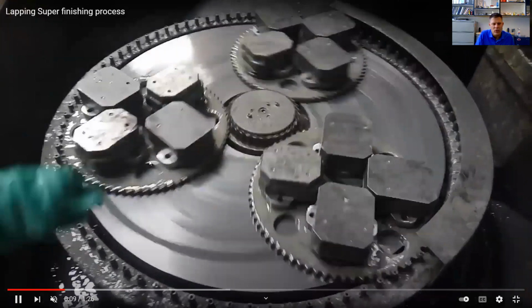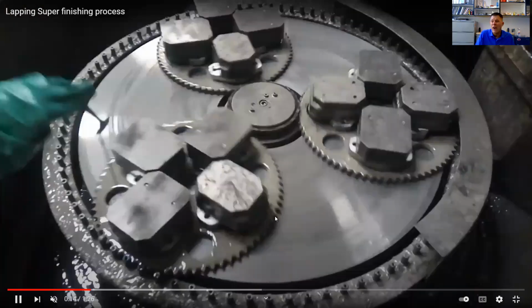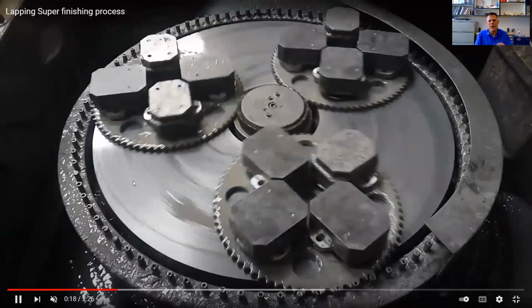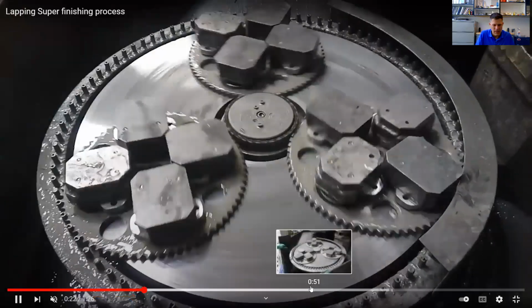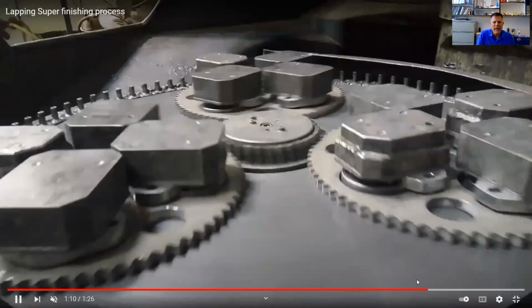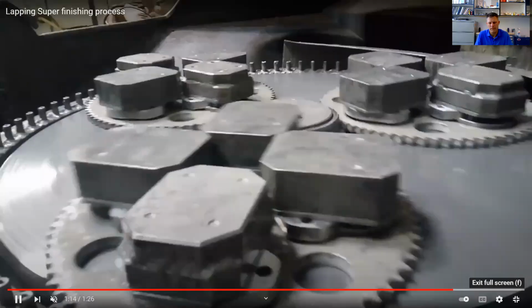The parts are underneath it. These are just weights on top of the part. The parts are actually underneath that. And all they're doing is removing a small amount, finishing the surface of that part to a real smooth surface finish. It does this for like a minute and a half. It continues to go, and they get a nice orbital motion, so you're not putting swirl marks in your part.